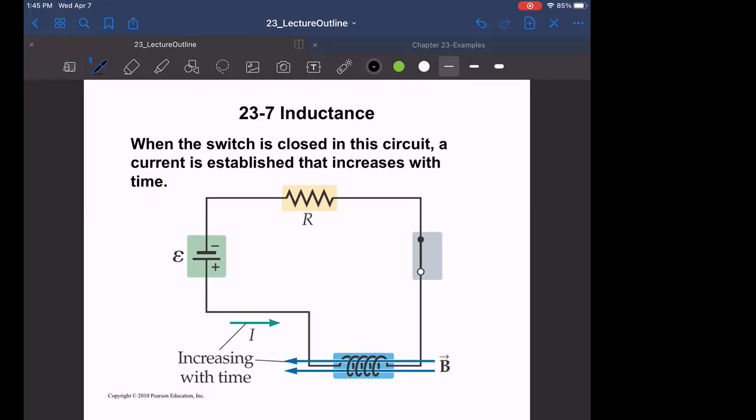A lot of things you can do are called high pass and low pass filters. Like if you're making a stereo system, you can filter out high frequency and low frequency sounds to go to different speakers, like the tweeters versus the subwoofers. You can do that using capacitors and inductors. However, typically you might as well just use the capacitor, because capacitors can be made a lot more consistently. It's hard to make inductors that are always what you intended them to be.